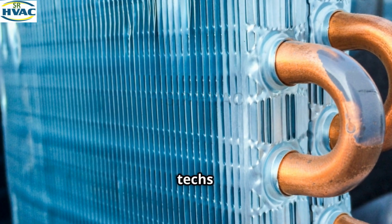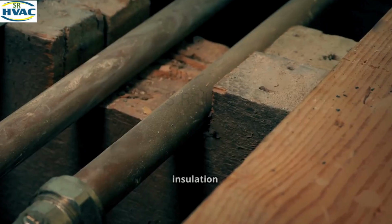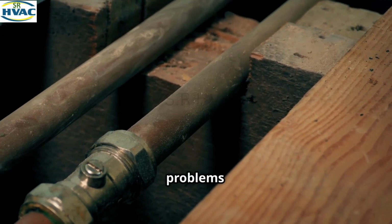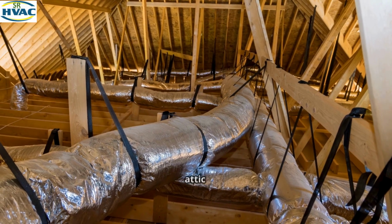Here are common mistakes techs make when it comes to heat transfer. Skipping insulation on refrigerant lines, conduction loss. Ignoring poor airflow, convection problems. Not factoring radiant heat load in attic systems.